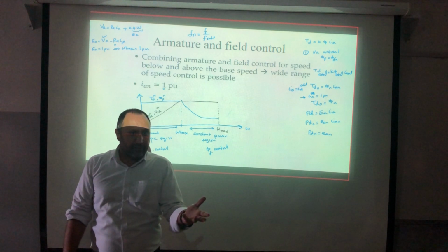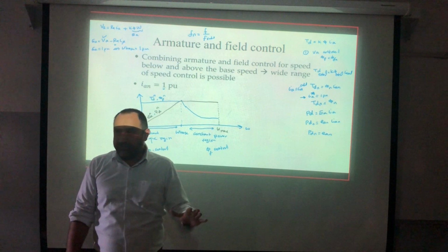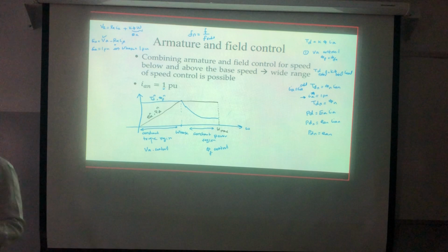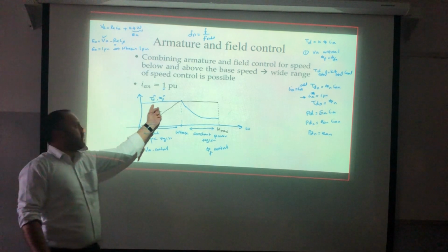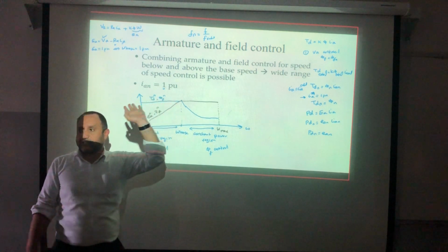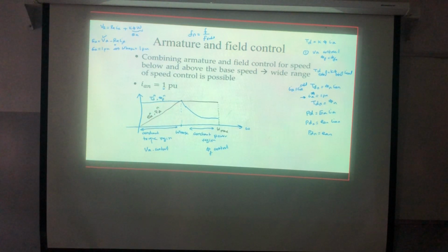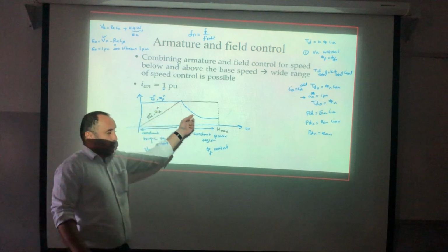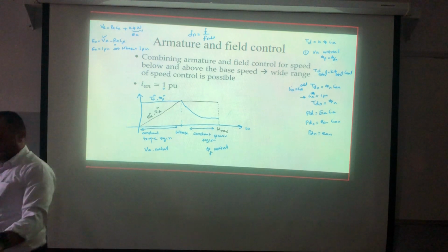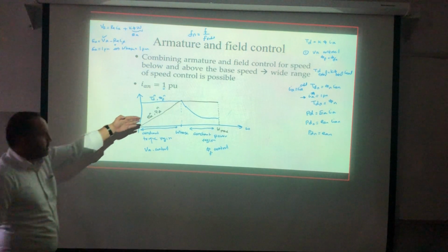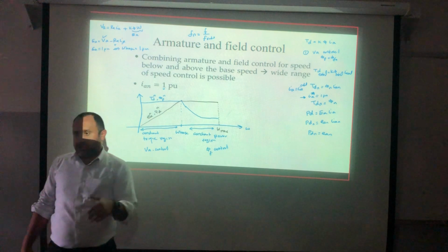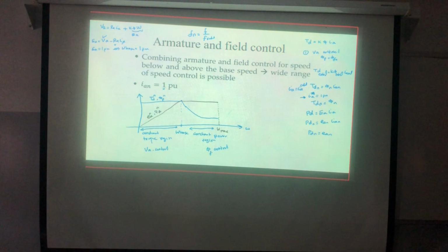Now this torque is equal to what? 10, 20, 50, this depends on what? Here I'm assuming that the maximum capability of the machine is the rated, the continuous mode of operation. I have another curve, which is a wider curve, and this one we call the transient capability. Now here the same. This is the field weakening. I can go on speed up to omega max. This omega max can be twice the rated, 3 times the rated, 4 times the rated.